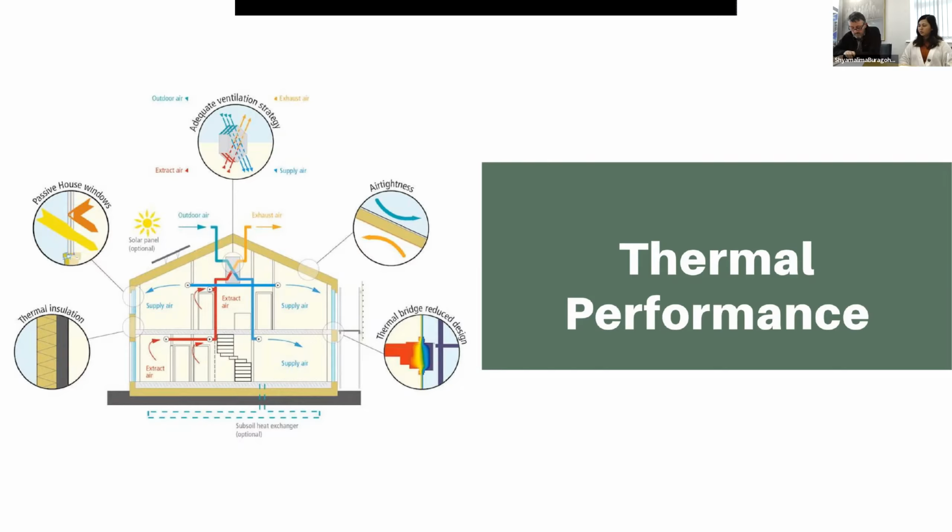Building services within a building, their pipework, extract fans, controls, building management systems, all play a role in improving the performance, as does passive stack ventilation. But if you do incorporate passive stack ventilation, it needs to be designed in from a very early stage where the shape of the building would cause it to naturally ventilate itself, and you don't need mechanical extract fans to suck air out or blow air in.